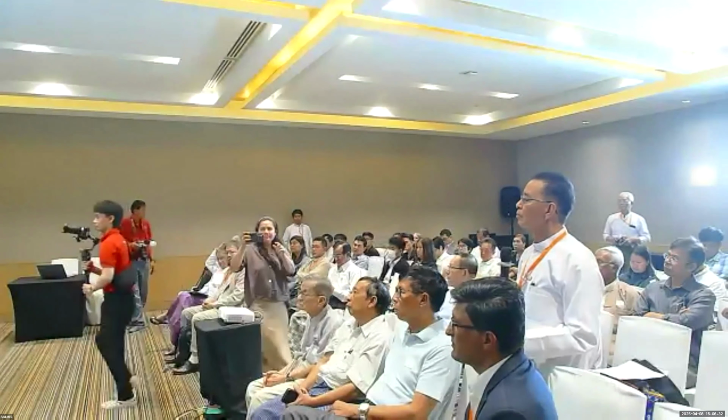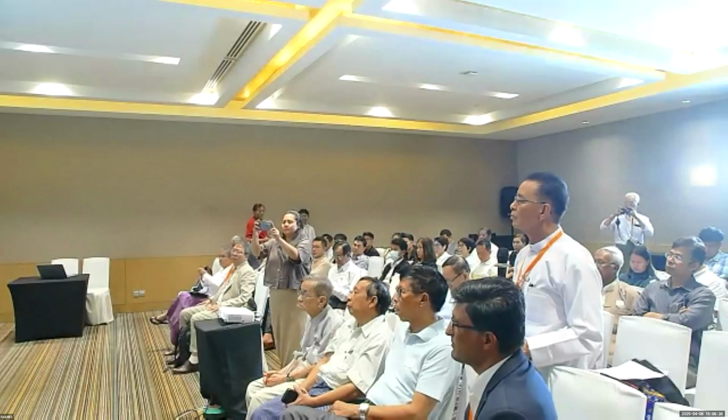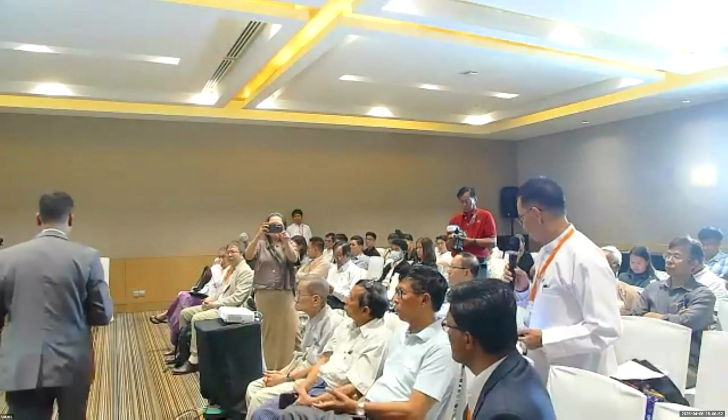One is a hospital in Istanbul, Turkey, which I visited, and a few buildings in the United States, especially the University of California library building, which was a little more than 100 years old and was lifted up. Otherwise, it is extremely expensive if you're doing a retrofit. If you're building a new building with base isolation, it is still expensive, but not as expensive. Great. Thank you very much.